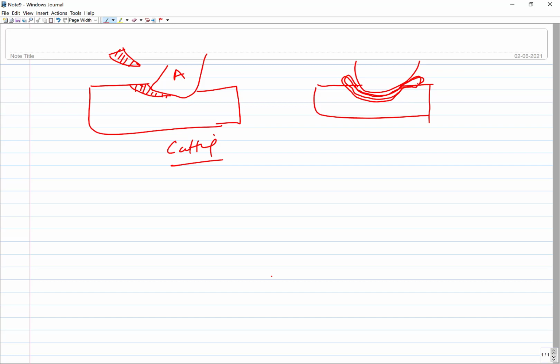It's just like pressing your finger in wax, the material will flow sidewise. If you scratch, a part of the material may come out, which is cutting, but a part may flow sidewise. So one situation is where cutting is happening. The second situation is where the material is getting displaced sidewise. This is called plowing.